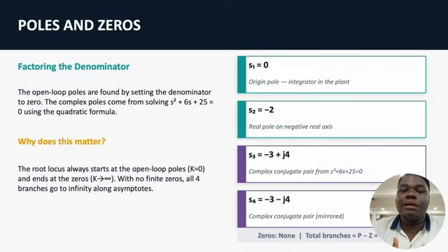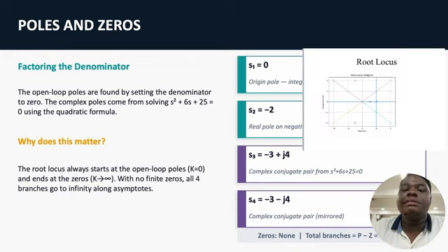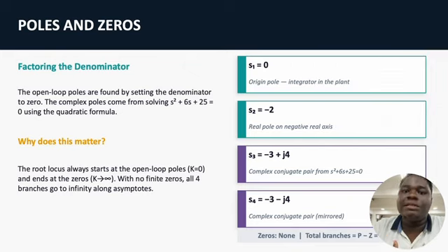My name is Oliver, and I'll tell you why the poles matter. The poles generally tell us how the system behaves. For example, when the poles are on the left hand side of the plane, the system is stable. When on the right hand side of the plane, the system is unstable. And when the poles lie on the imaginary axis, the system oscillates. So the main purpose of the poles is to tell us where the root locus begins, the number of branches, and where the system oscillates. With this understanding, we can move on to determine where the root locus exists on the real axis.